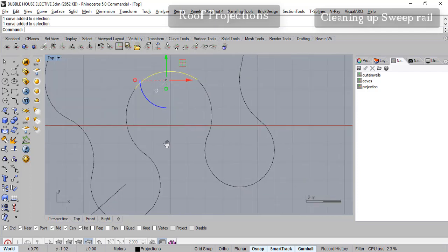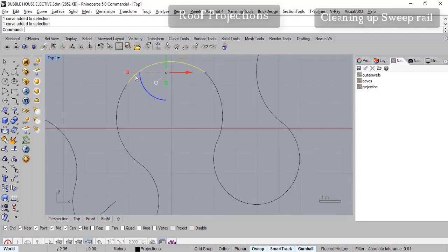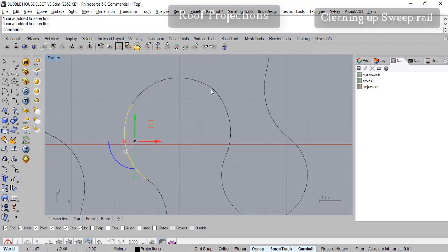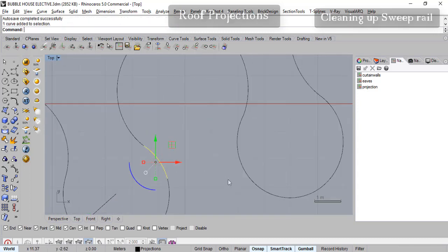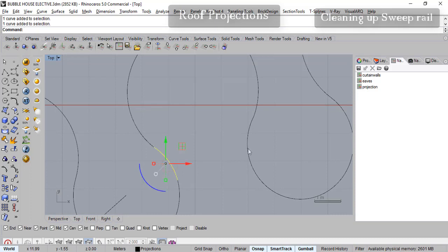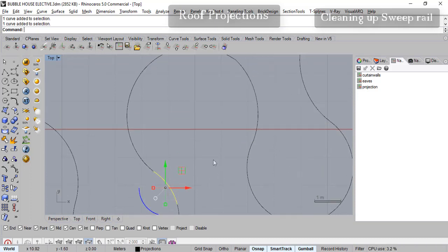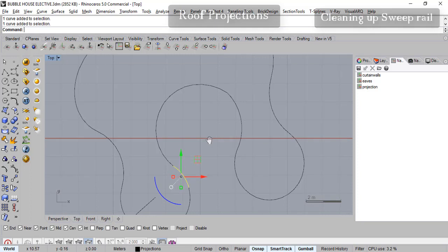So the way we can do it is we'll try to draw a circle which resembles this circle and which would be one single circle instead of all the small parts, because it's all smaller parts. While we did the sweep command, it kind of got divided. And also because it's very acute here, it's not joining up correctly. So this circle seems to be okay. So we'll use these two curves as the tangent edges, and we'll try to draw the third one here.